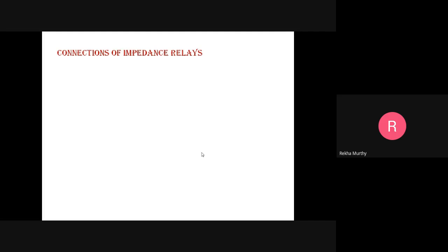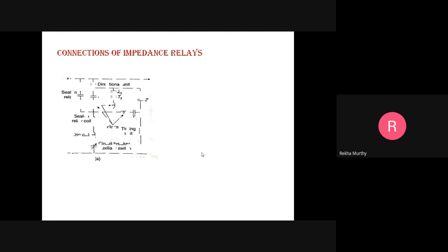So the same circuit what we had considered in the previous sessions, that we are going to look into after. So that circuit connections consisting of the circuit breaker, trip coil, the contacts of a directional and impedance relay, flags, timers, all that, which will be present here. Okay, and here Z1, Z2 and Z3, they represent the impedance relay. And whereas T2, T3, they are all contacts of the timer for the second and third zone respectively.